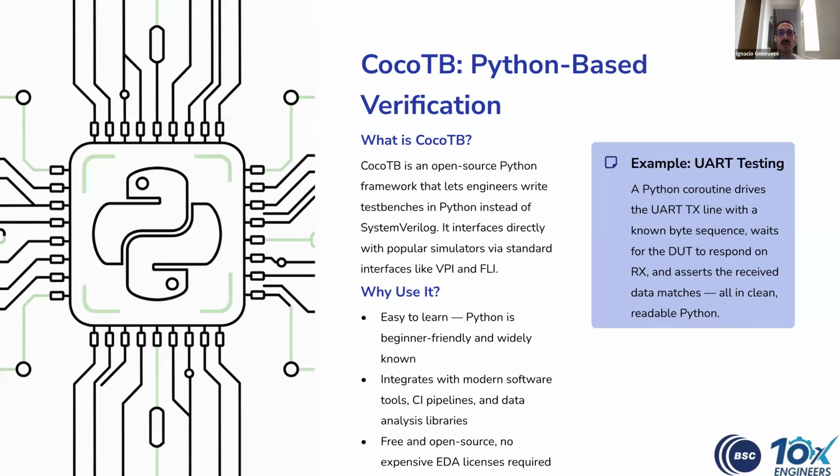SystemVerilog and UVM. And one advantage of CocoTB is that it integrates really simply with software development tools like continuous integration and continuous development pipelines. So we can write our test benches in Python and interface these test benches with the simulators via a very low procedural interface for interfacing with C or with the foreign language interface that these simulators provide.